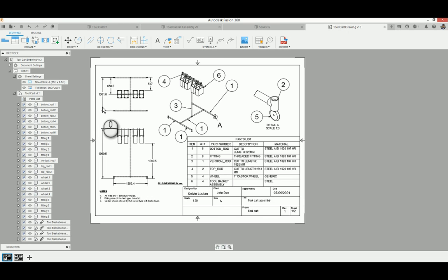That is what your first drawing does: you show the general dimensions, the width, the height, etc. And then you begin to label the components that make up the assembly. We put an isometric drawing here because sometimes this might not be too clear to visualize. The isometric drawing gives you a 3D representation, so you can actually see what's happening.